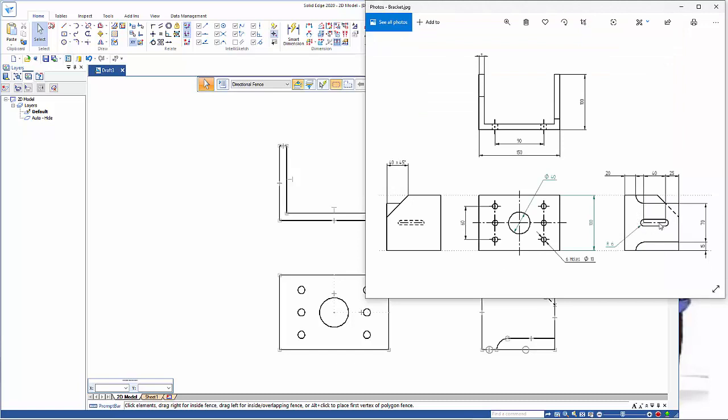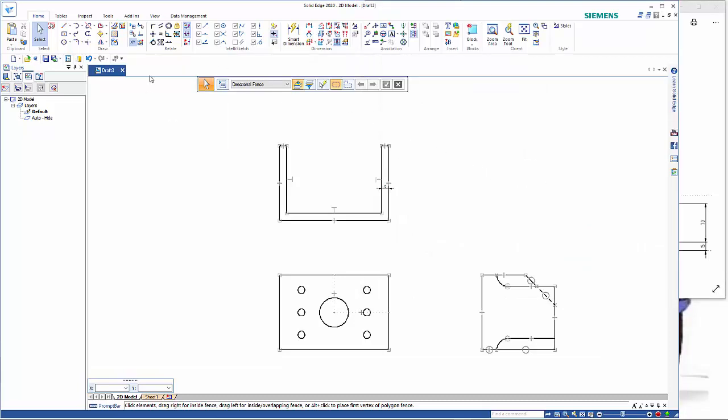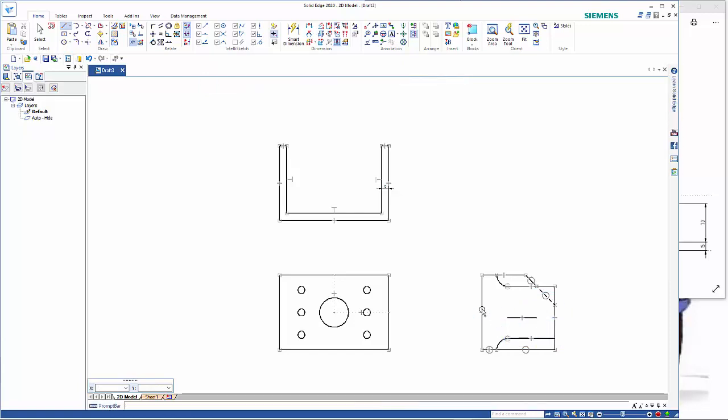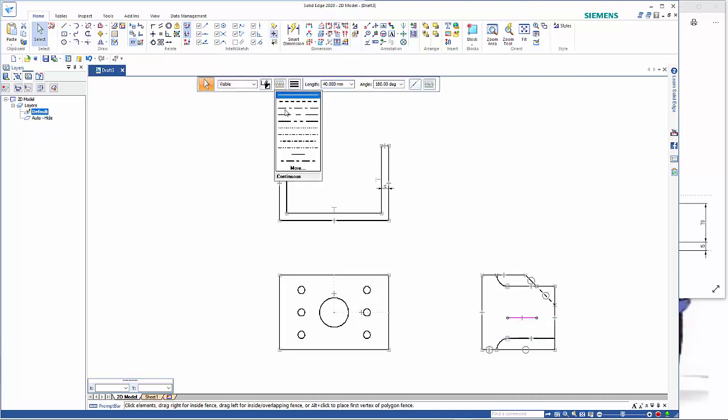So this is sort of the center line. It's going to be 40 long, 25 in, and it's centered around the center of the part. So if I draw a line and use my reset origin to here, Alt X, 25, tab across 0, and then I can start drawing over here, and it's going to be to size as I need to. So I'm just going to click on there and change that to a center line as well.